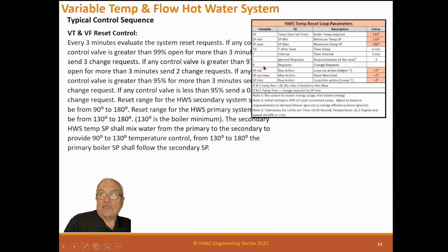All right, here's that standard hot water temperature reset loop parameters. And it's the same as the others. 140 degree is our set point, 130 is minimum, 180 is maximum.